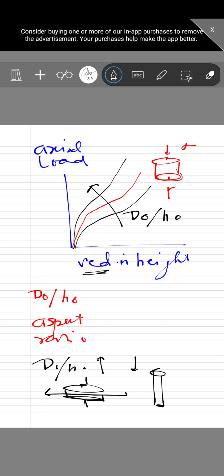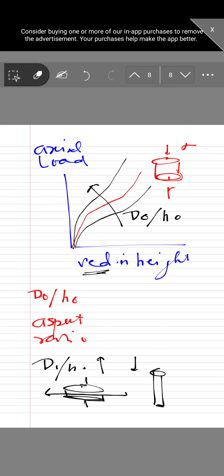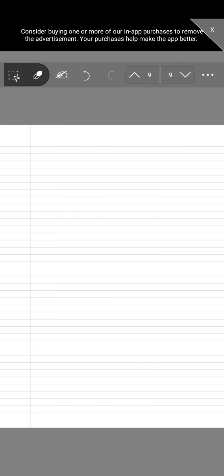Now these cone-shaped zones approach and overlap. It's called cone-shaped mainly because, see, this was the initial cylindrical shape, and this is the free flow region, where the friction is less active, while more frictional force is at the clamps.